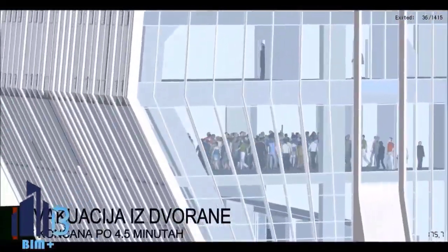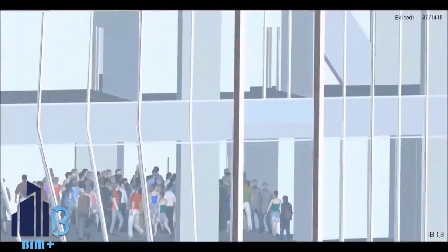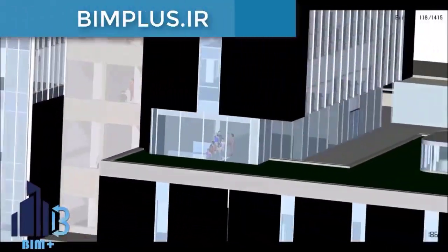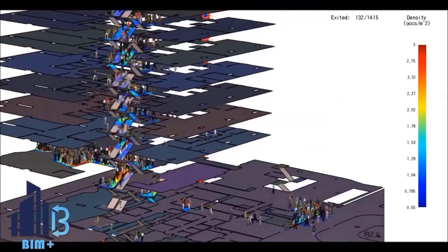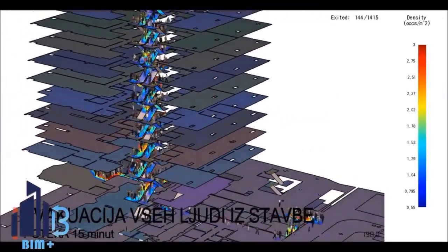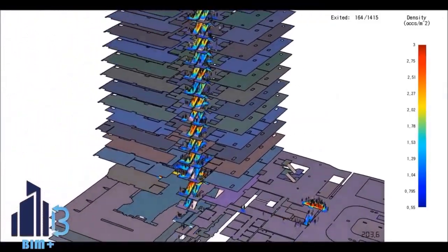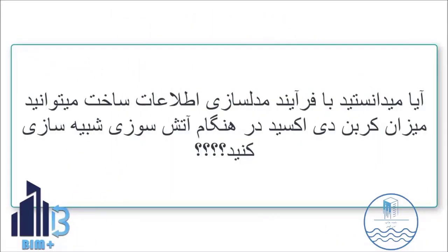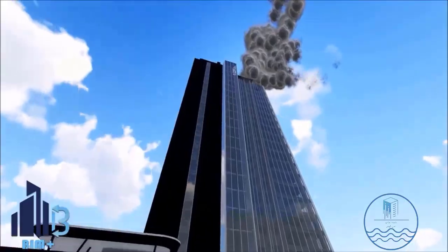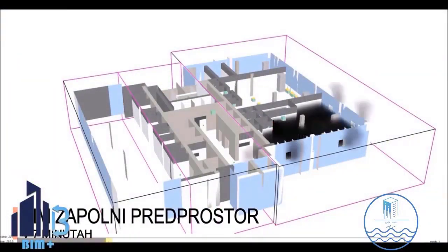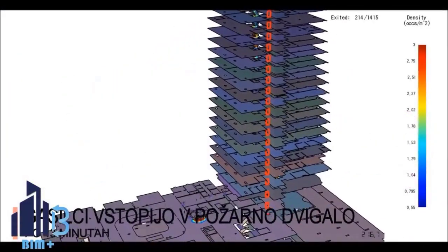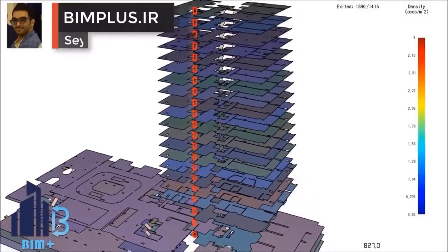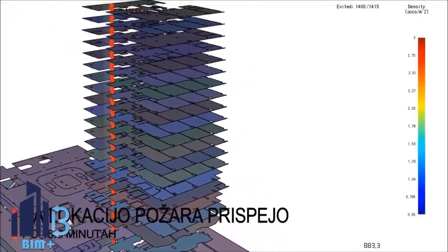Based on the optimized BIM model, various stages can be implemented, which are briefly explained in the following. 1. Fire scenario. In this model, you can simulate a fire in which the time and volume of smoke caused by the fire and the activation time of equipment, such as sprinklers, are modeled.